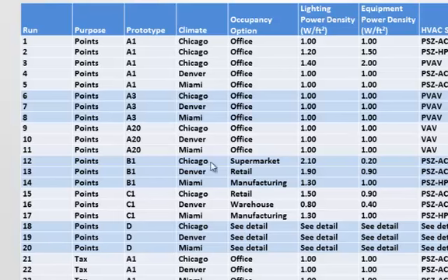We also model these in 3 climate zones, Chicago being a rather cold climate, Miami a hot, humid climate, and Denver a dry climate. And these climates will enable us to make sure that the economizer requirements are correctly specified in the baseline building.